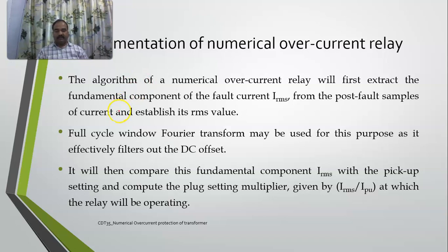Next, once you get these basic values of time delay or time setting and pickup value, you must be able to extract the data from your main signal. Let us suppose I take a power system circuit. The data is obtained here, and this may consist of some harmonics. So the next step is that you should extract the fundamental component.